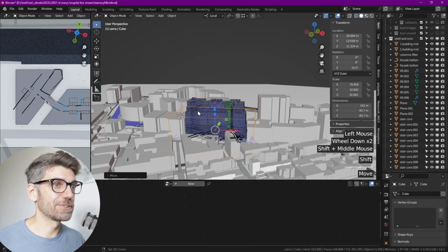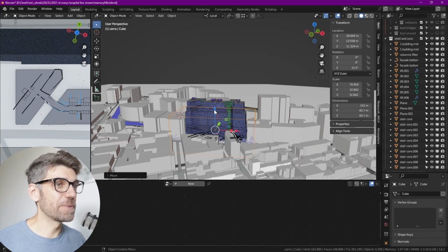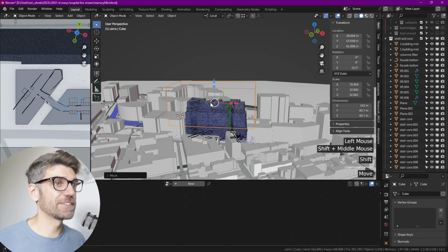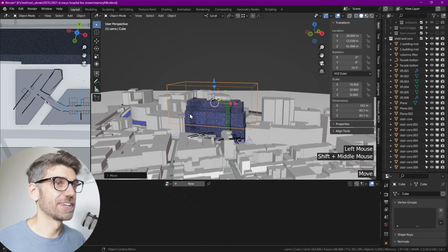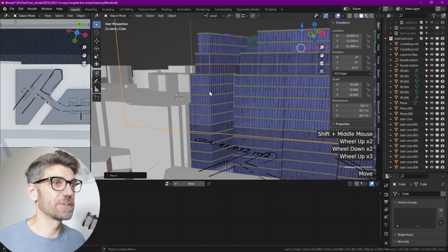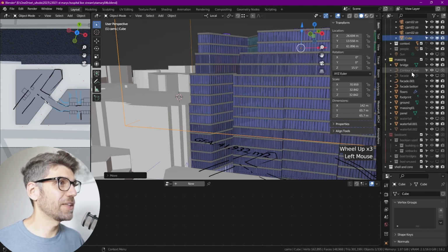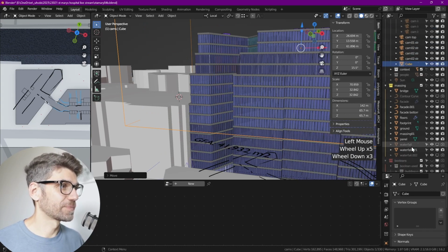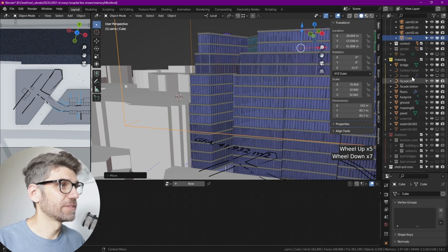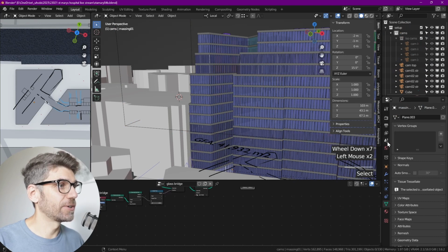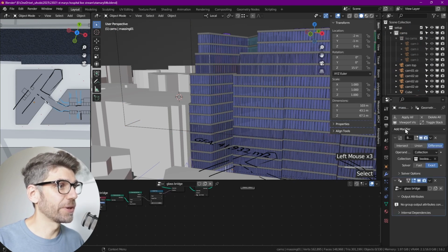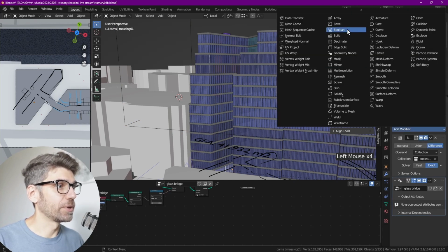Okay, so how shall we do this? Subtract or intersect? Doesn't matter really. Let's just do it for clarity's sake as a subtract, so we know that we're getting rid of everything that's on top of there. And now we're going to do the magic with our massing. So here's our massing, and onto it, we're going to add a new boolean. So add boolean.